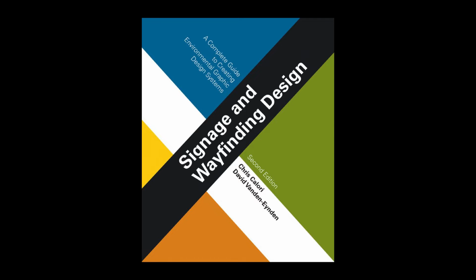See Figure 6.5. The mounting or support structure for each of these types of mounting can be either hidden or expressed, leading to the following overall sign forms listed below and shown in Figure 6.6. Note that all of these types of sign mounting can occur at various heights, and that the ADA and local codes can affect those heights as well as other sign dimensions, as touched on in Chapter 5, the graphic system, and later in this chapter.